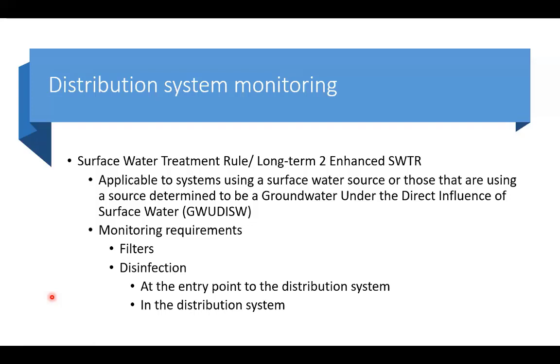But surface water systems, like groundwater systems, have significant requirements for monitoring. So for instance, the filters must be continuously monitored for filter effluent turbidity. And with regard to disinfection, the systems must monitor the chlorine residual, and what they're monitoring is free chlorine residual, which is the same measurement that you did in one of the labs.